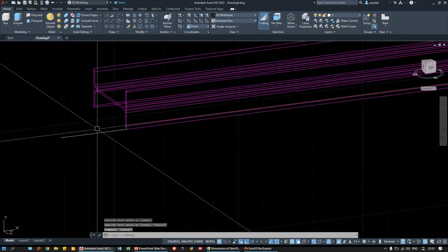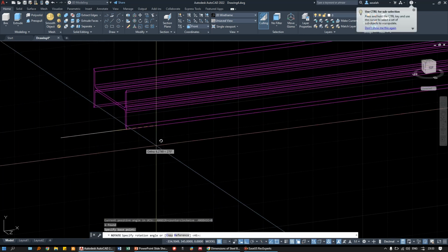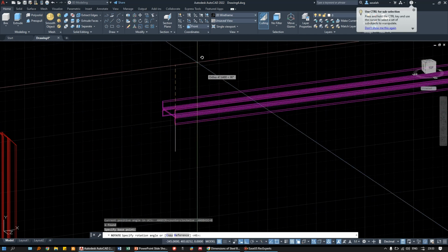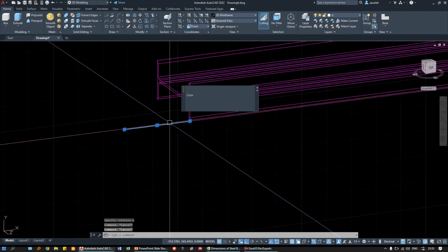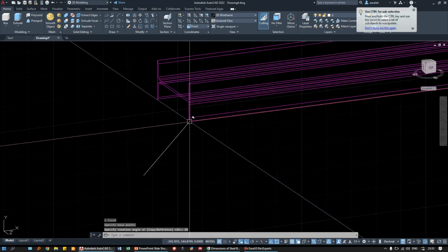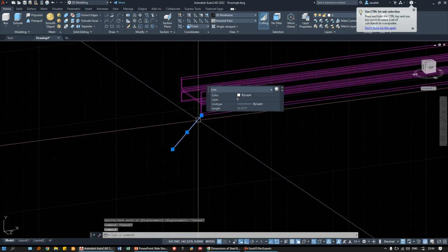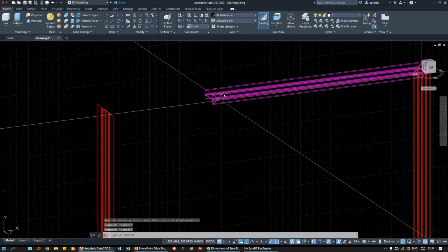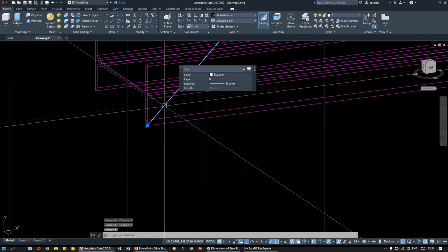I'm going to draw this line, and then I'm going to rotate it. Now we can use the normal rotation command because I don't care about 3D rotation. I just want to rotate on this face, which is the front one. So I'm going to rotate this line by 45 degrees. Let's move it again. But as we can see, I don't want to do a cut here. If I cut like this, they will not match. So I need to flip this line.